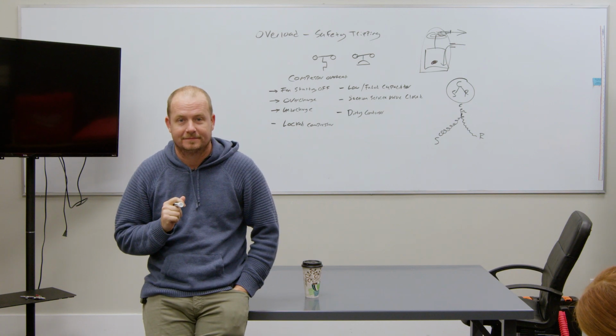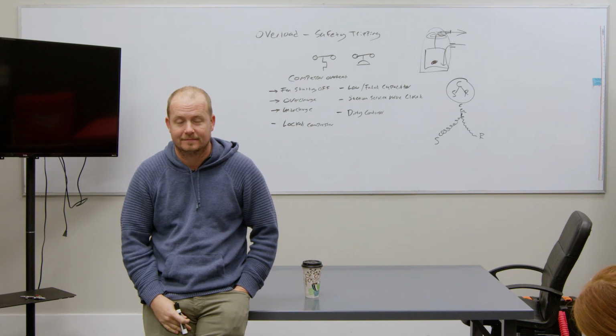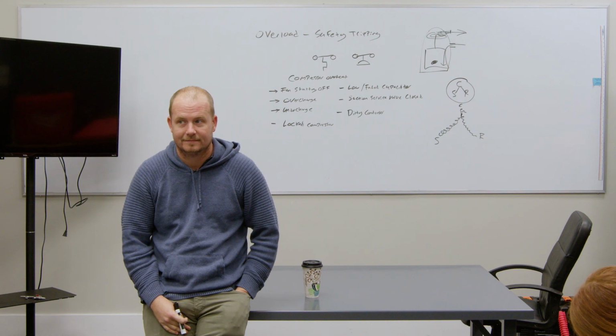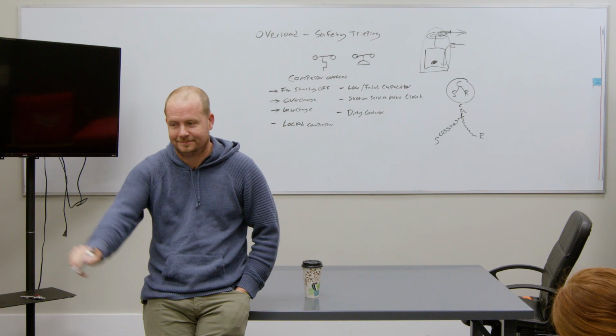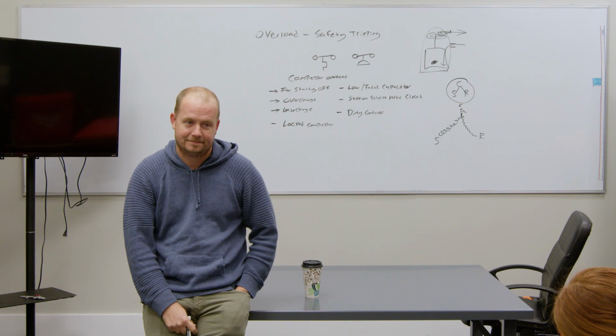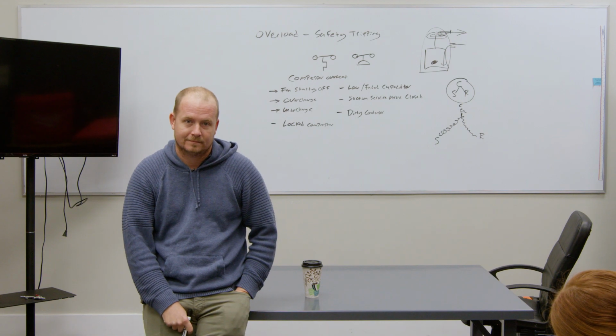It's unique. It's multiple circumstances. I think it could be like in that long line set, slightly dirty evaporator coil, and low charge, a combination.